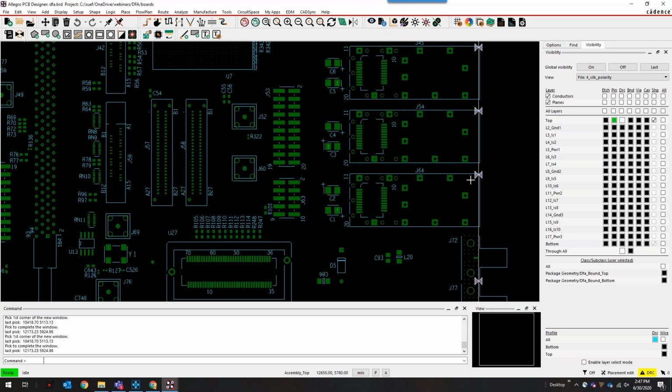So Gerber data is really an outdated data. Most manufacturers now have tools like Valor, for example, and by giving them just Gerber data, which is just dumb data, X and Y locations, on, off, that's all it is, they have to manipulate that data. Whereas if you give them the full ODB++ data, all that information is integrated into that file.